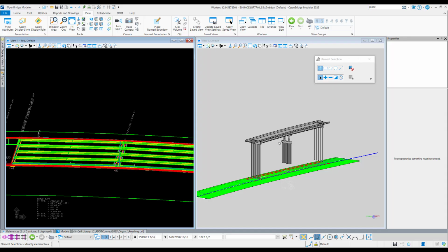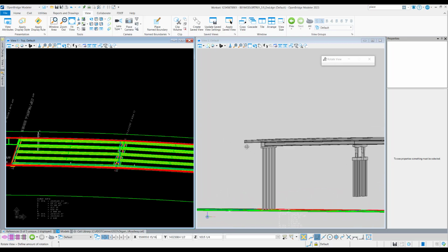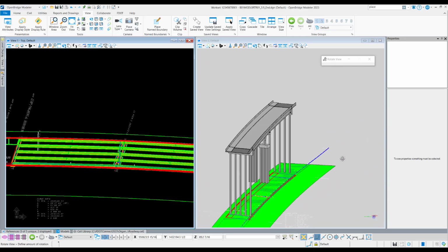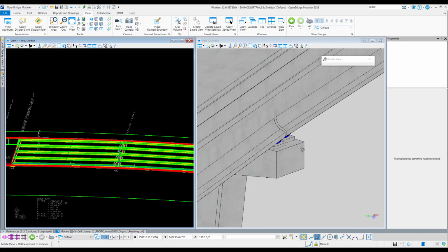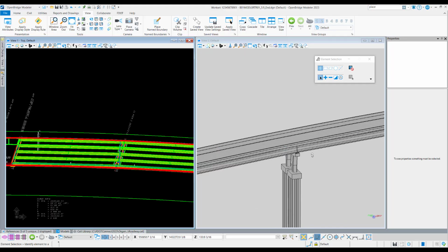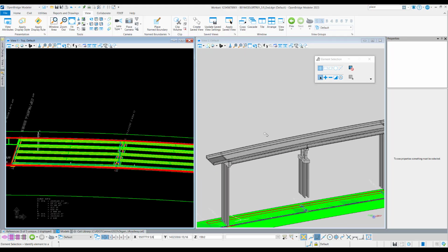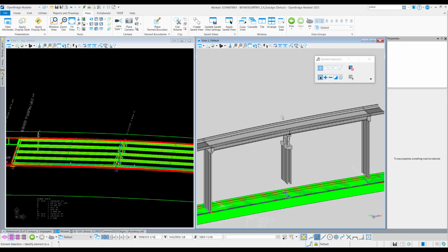You can also rotate around freely if you hold down Shift and you hold down the click wheel and kind of rotate around. That's sort of like a freehand rotation. So you can zoom in and then rotate around. It's going to rotate about wherever your cursor is. So some people can do that pretty well, and others find it a little bit disorienting and kind of difficult to do that freehand rotation.